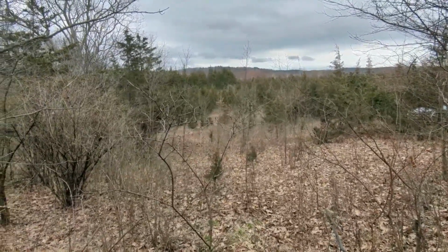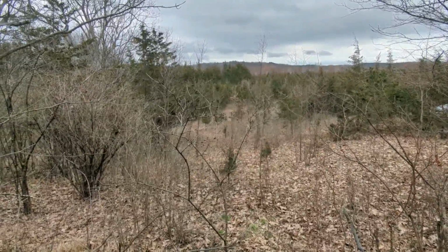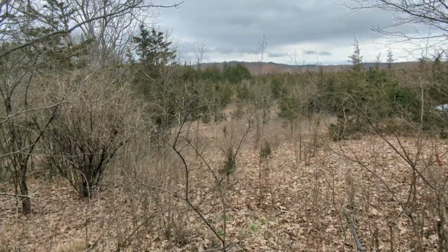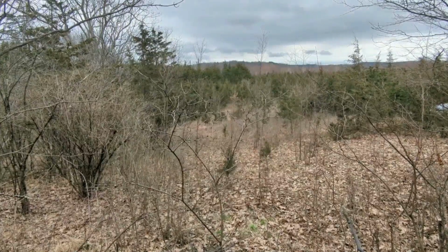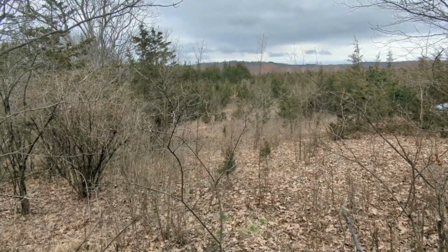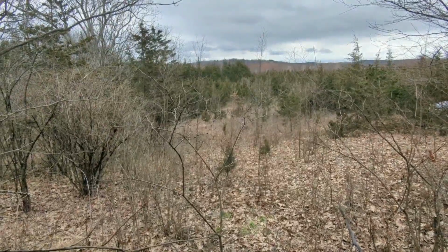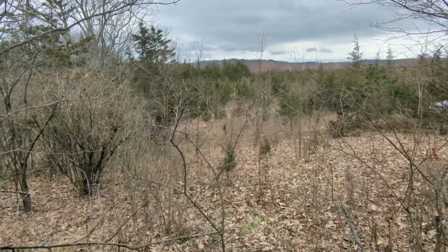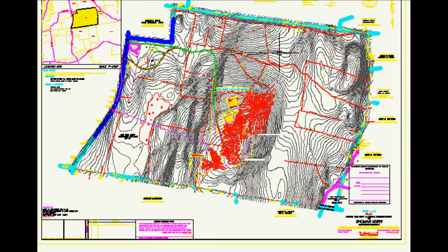And the reason for that is things like regulations here in New York State require that a well be at least 100 feet from a septic system, provided that it is uphill in elevation from the septic system. And if it is level with or downhill from that septic system, then it is required to be 200 feet away from that septic system. So now I see you probably get a picture of why elevation ties in so importantly to things.